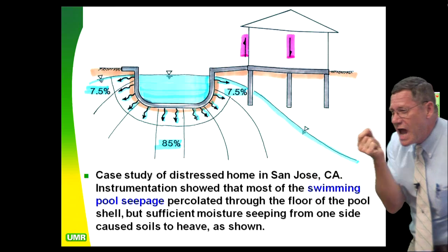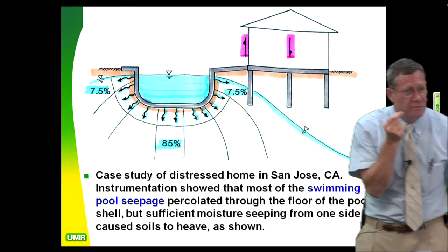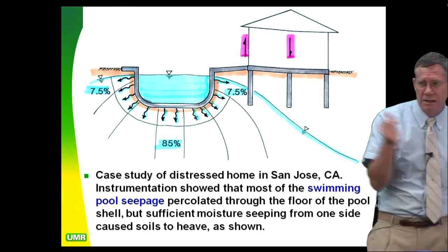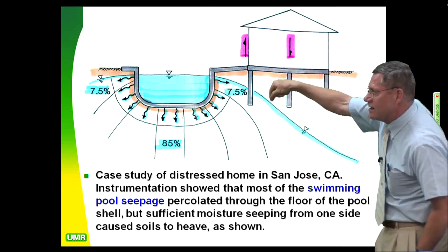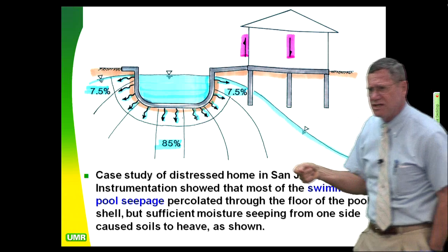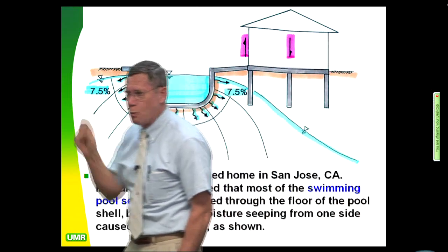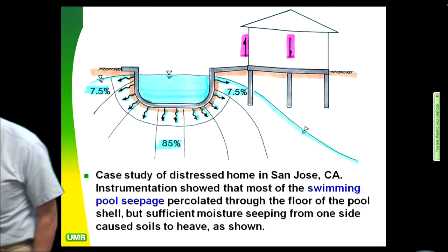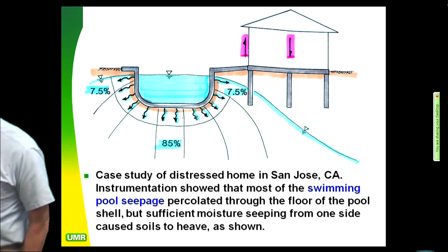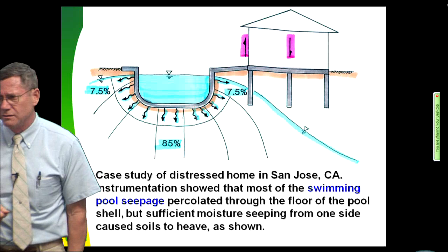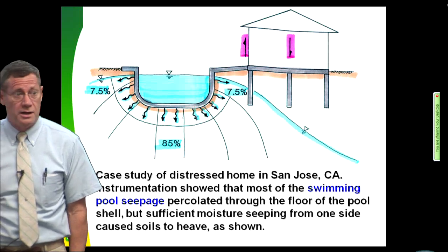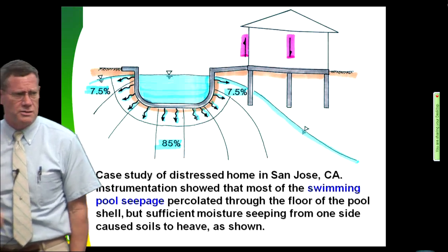It's the most accurate tool in your tool chest for seeing the zone of saturation when you're out putzing around structures. Because as soon as you hit the saturated zone, you'll see a 6 to 8 degree change in 1 centimeter. Boom! You know right where it is. You put a piezometer out there, you have to instrument it for 3 months to find out where it is. Takes you forever. Cone pen is great on seeing the zone of saturation.